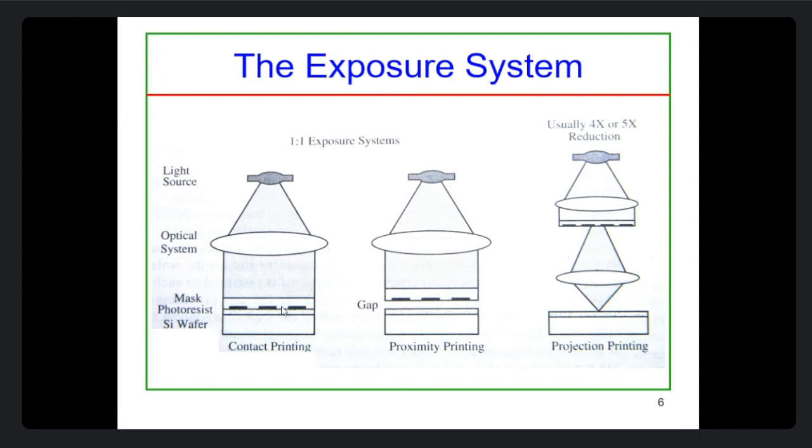In that case, it should be called a mask. But in the projection case, the output of the circuit designers contains the pattern or image corresponding to a single die, which will eventually be converted to a chip. That is why it is called a reticle. So technically, you should understand this difference.